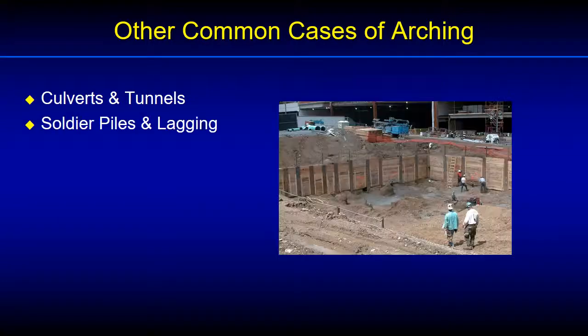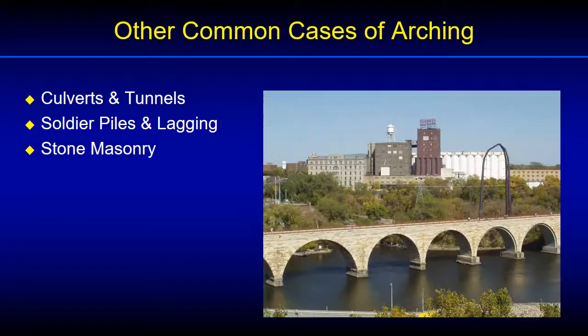Soldier piles and lagging is another application where arching around a vertical opening between soldier piles allows the relatively lower strength timber lagging to support the soil in between the piles. And of course, everyone is familiar with stone masonry and structures going back thousands of years, from Roman bridges to arches over doorways and windows.